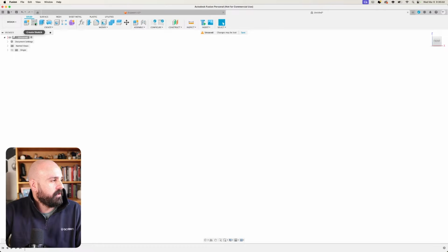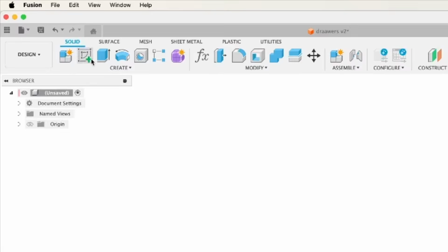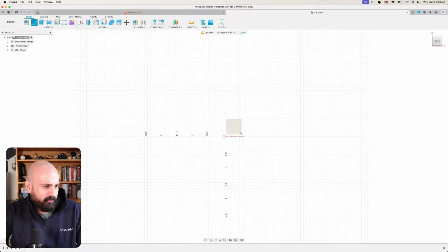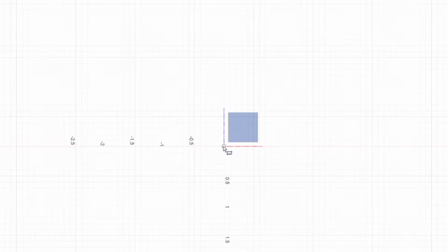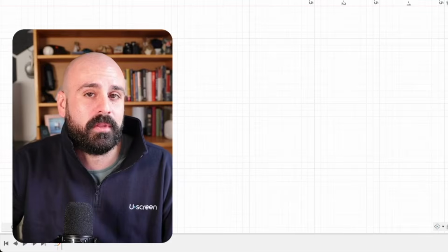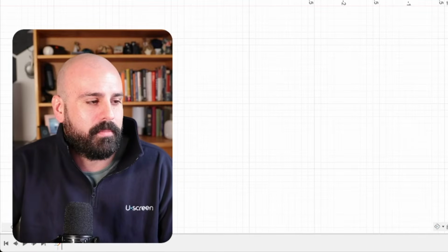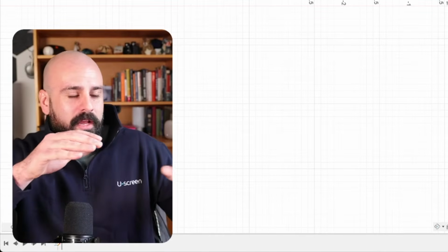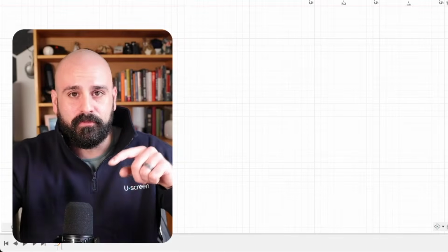So now I'm on the front view of this profile. There's nothing here yet, but I'm going to click on New Sketch. And I'm going to start off by pressing R for rectangle, and then start in the middle spot right here. But as you can see, it's adjusting the actual rectangle that we're building. So this is where the parametric modeling comes into play. I'm not going to just type in whatever measurements here. I'm going to reference all those parameters that we just made earlier.